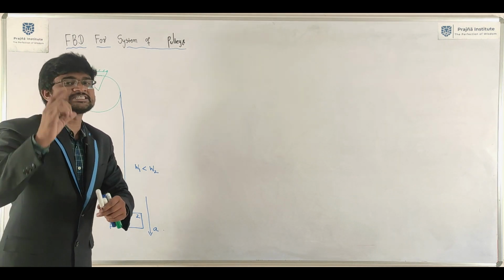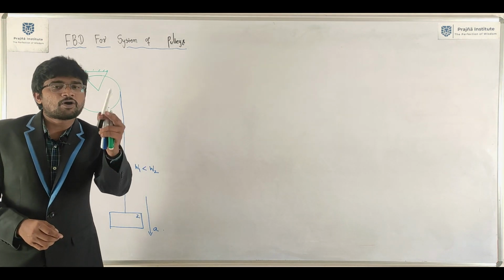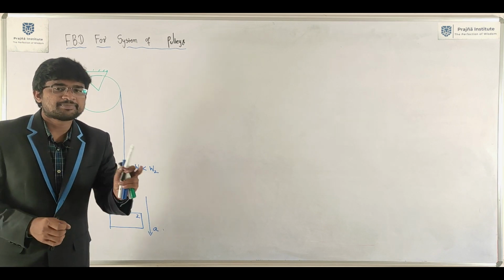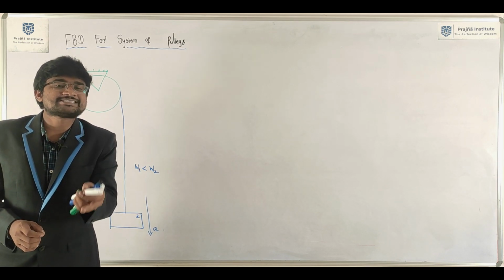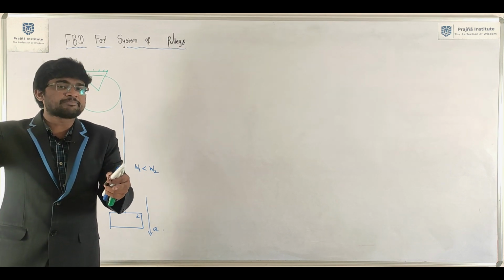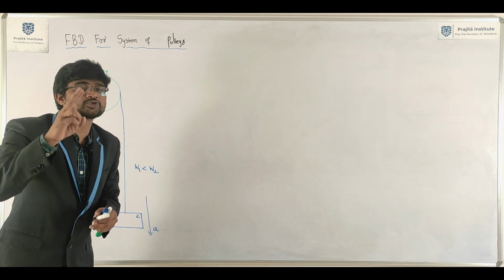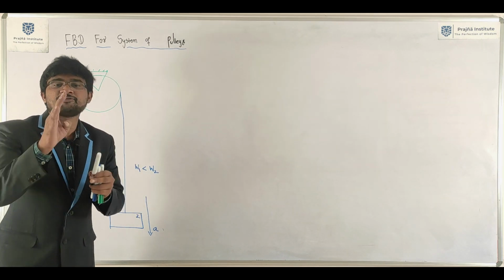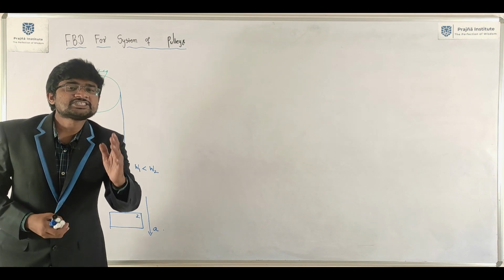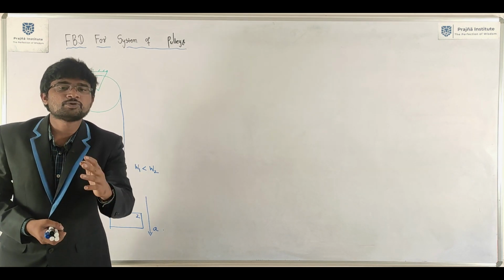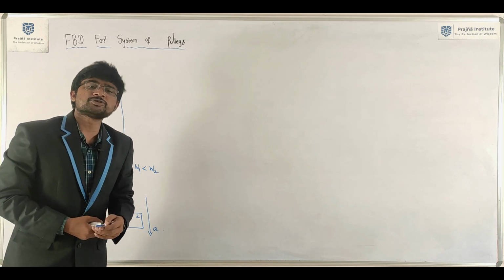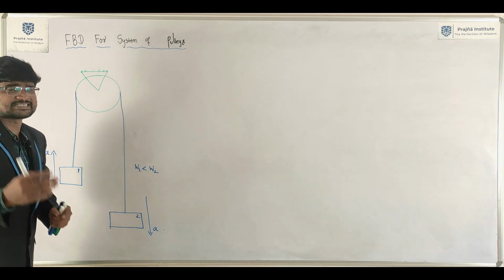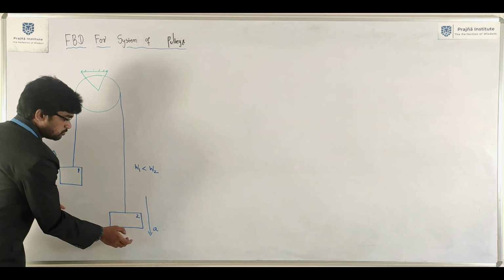What are they? First statement, weight of the body always act vertically downward direction. Next, tension always pull the body. Third statement, normal reaction always act perpendicular to the surface. Fifth statement, at every point of contact on surface, two normal reactions will be acting, both are equal in magnitude and unlike in nature. Finally, fourth statement, inertia force and frictional resistance both always act opposite to the direction of motion of the body. Now, just apply those 5 statements to draw free body diagram for the 2 blocks.